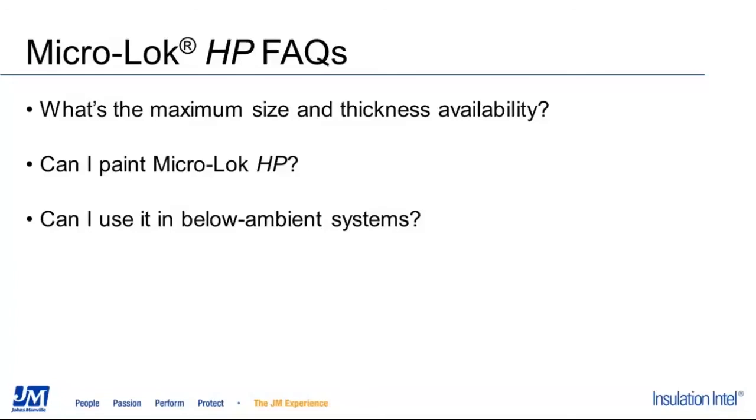So when anything is added like paint, which could function as a fuel source, we can't guarantee that our product with the paint is going to continue to meet that rating. So you could install our color PVC over pipe insulation, which would be a great alternative to achieve a certain color match, and that would allow you to maintain that 2550 rating as well as our manufacturer's warranty.